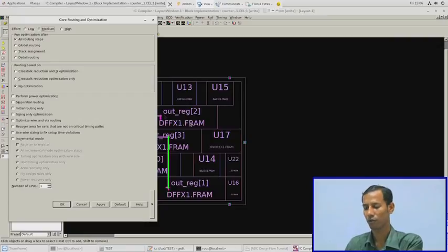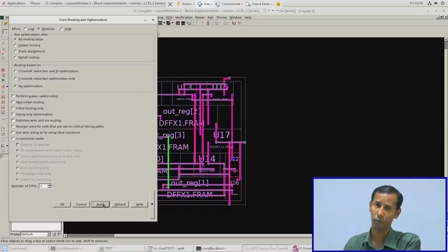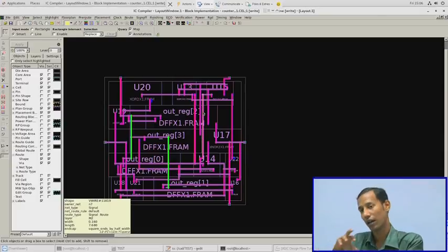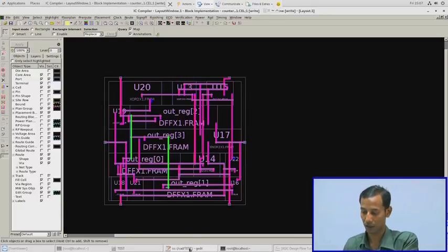This is a 4-bit counter basically. For a 4-bit counter, it is not at all required, so that's why we are not selecting it, but there are options where you can select and carry on with your further design. That will be provided supplementary to this. Once I have placed it, you see this color is already routed, that means each of the cells has now been connected, each of the MOS is connected to each other based on this particular netlist file.